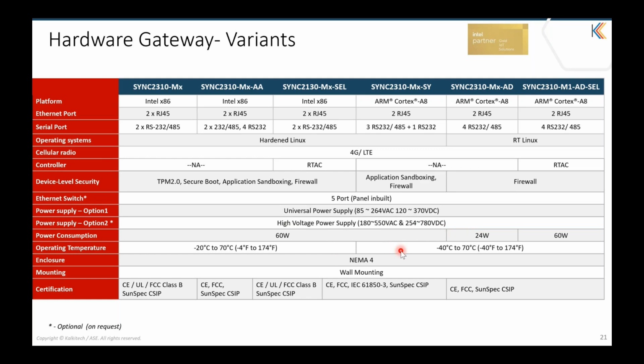And there are certifications which comply with CE, FCC, SunSpec, CSA. Some have scored the certification for IEC 61850-3, which enables this particular device to be used for a substation kind of environment as well, with hardware level EMI EMC compliance provided in this particular device.